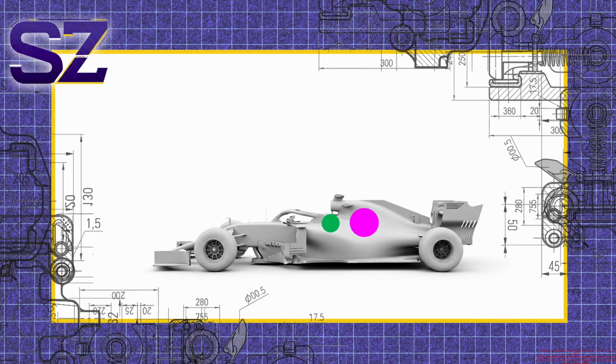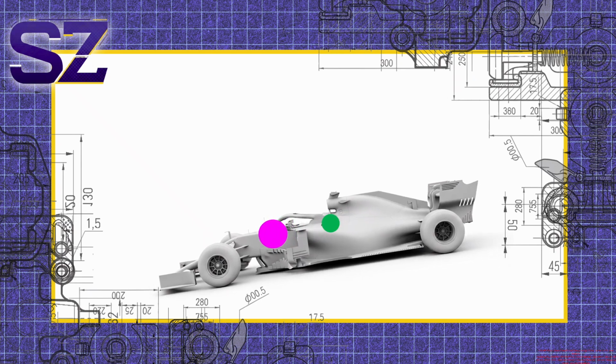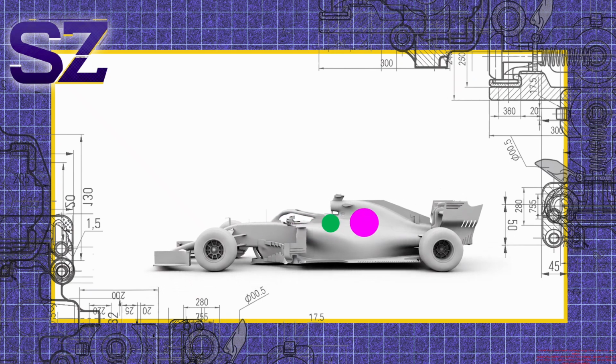Under braking, especially with rake, which is where the rear of the car sits higher than the front, the aerodynamic center of pressure often moves forward. That adds even more load to the front axle. The challenge is to maintain both mechanical and aerodynamic load transfers simultaneously. Engineers can deal with this in a few different ways.